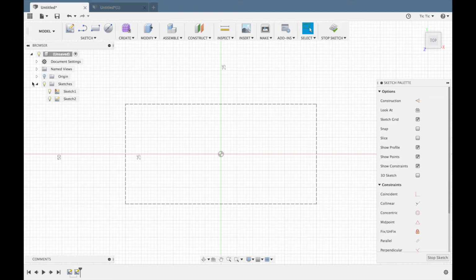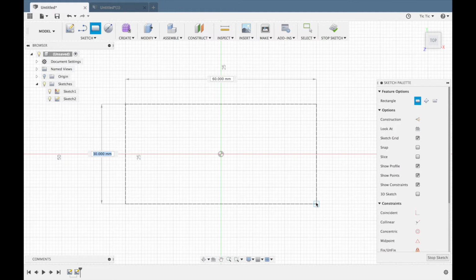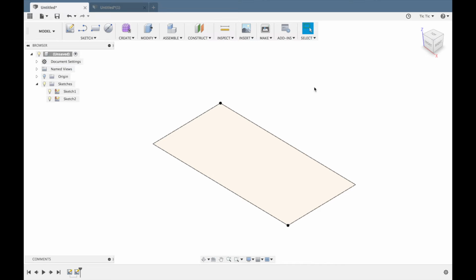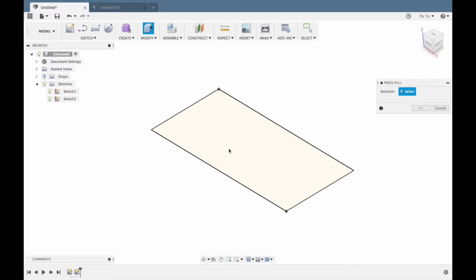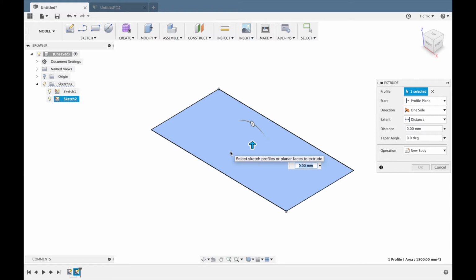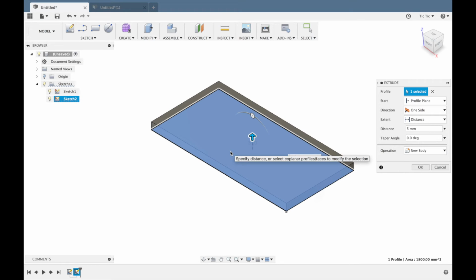There should be two sketches if you drop down this little thing here. So open it up. There should be two sketches in here now. This one here is the pinned one, your outside sketch, your bounding box, and this sketch here is the one we're working in right now. So I'm going to use my rectangle tool, and I'm basically just going to draw a rectangle which perfectly locks to my bounding box. Then I can hit stop sketch, and I can now make my actual name tag base, and I'm going to hit modify, and I'm going to pull up 3 millimeters and press OK.